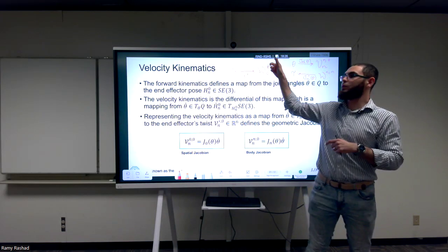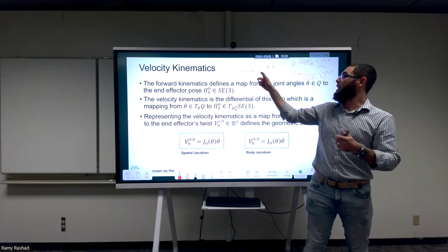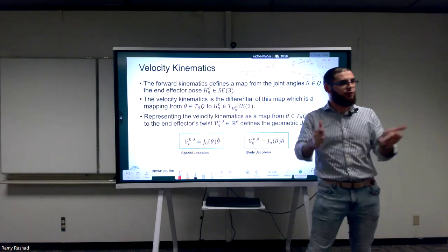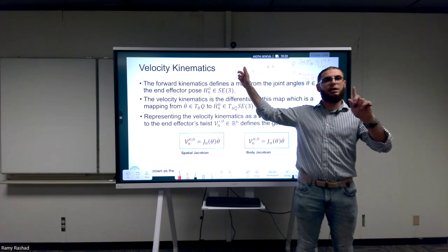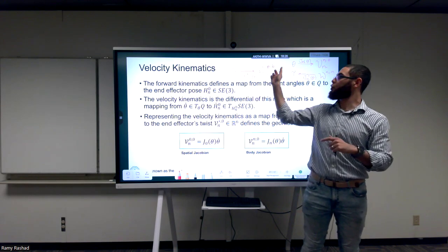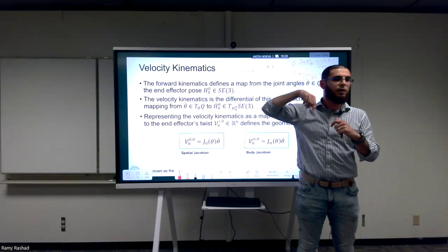So if I want to compute the wrench that makes the drone hover, M also depends on theta. Again, remember, it depends on the angles if you have something that's variable tilt. What's the thrust that each propeller should apply? Again, I would use this map in this direction, so I would use the M inverse, or try to invert it in some way.